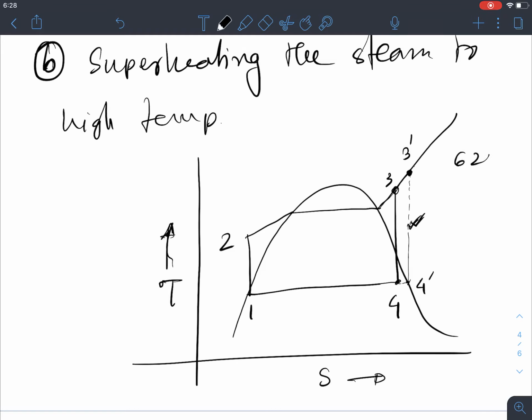So far the turbine blade material can handle 620 degrees C. So that's the maximum temperature, and we have to make sure the boiler output comes up to 620 degrees Celsius. I mean, everything evolves. Who knows, there may be some material developed that can handle up to maybe 1000 degrees Celsius, and at that time we can increase the temperature further, right?